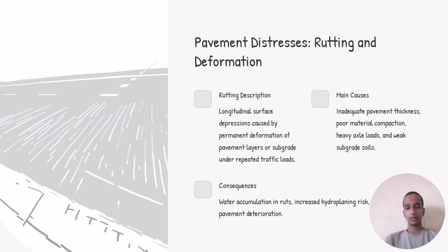First of all, now we will see rutting and deformation. There are these other two types of distresses, that is rutting and deformation. Rutting is basically the undulations in the road due to heavy traffic or other conditions, and the other conditions are like subgrade or subbase failure. If the subgrade is not provided properly, or if it fails, there are certainly undulations in the road. The upper surface will face undulations, and that is the first thing.